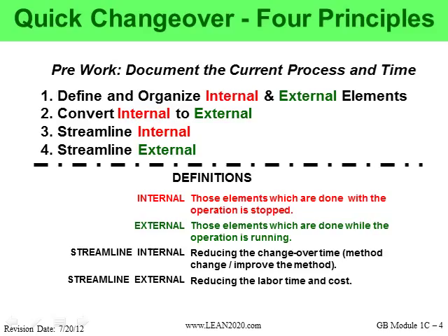So we're going to grab a small group of people and we're going to observe what's happening during the changeover. So we'll watch an individual or a group of people, whoever is normally responsible with this, and we're going to watch them perform the changeover. We're going to define what happens during the internal and external elements of that changeover. All right, we're going to document this in writing. We're going to document it with pictures, and if it's a short changeover, sometimes we even like to take videos